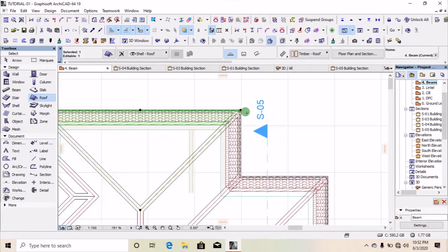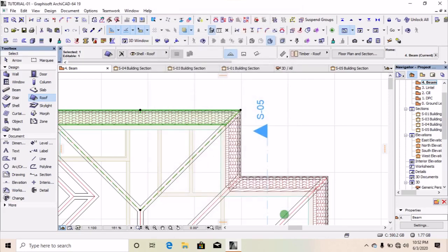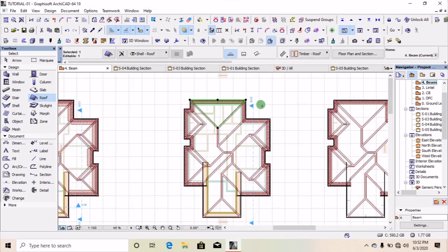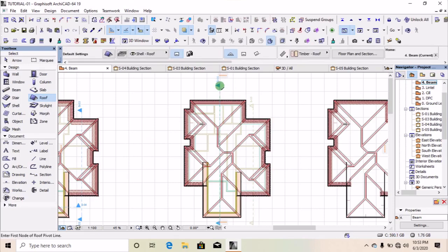Then change the settings, like as it is here. Change this angle here from this spot to this spot. Change the thickness to 25. Then link the surfaces. Now that is done, click OK. Then drag your section line to cut through that plane.